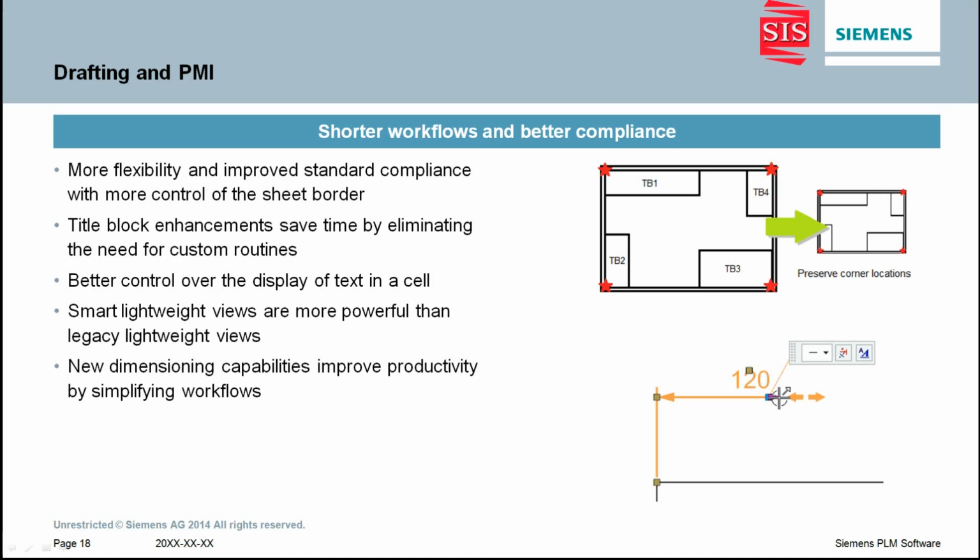Title block enhancements include automatic repositioning on sheet resize, being able to edit a table in a task environment, cut, copy, and paste support, better handling of date attributes, word wrapping support for cells, and user interface improvements.